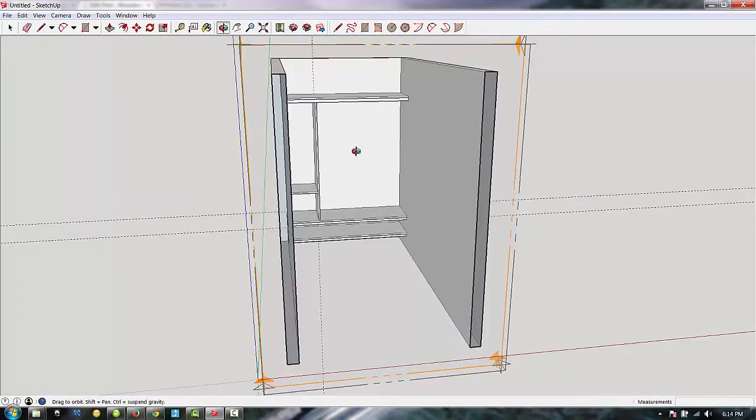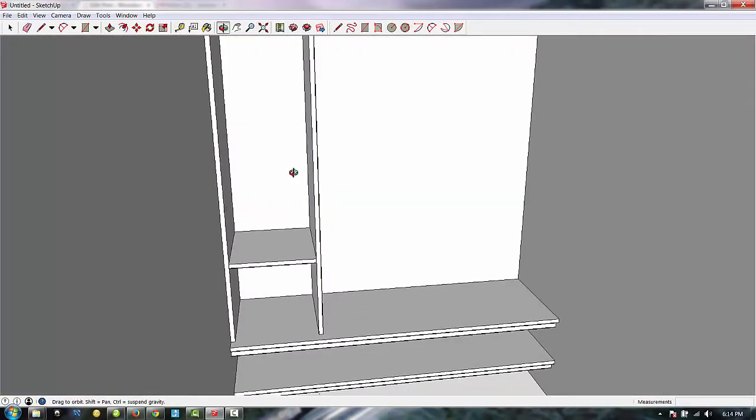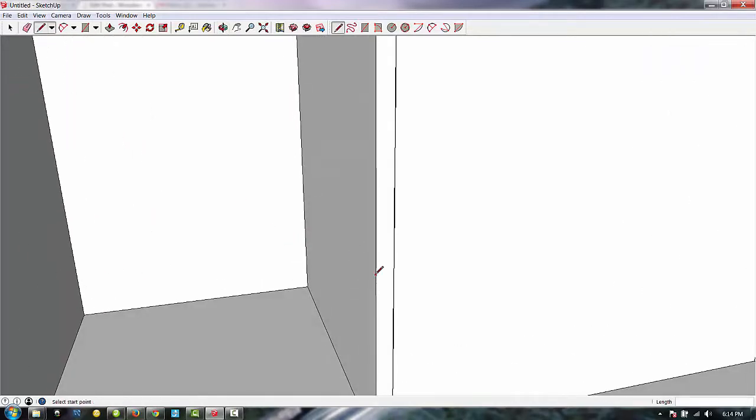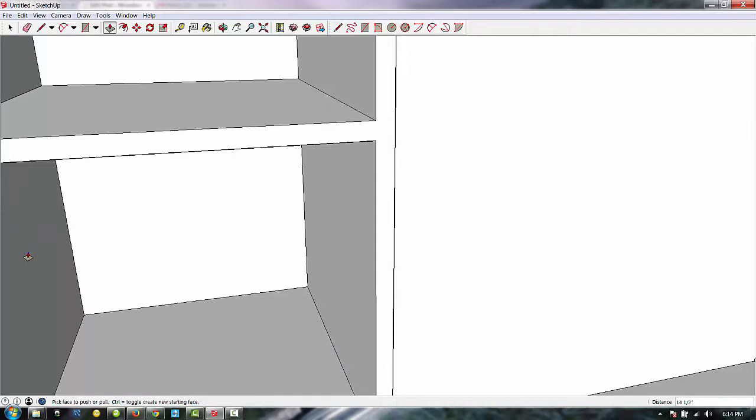Once again, in a wall, working in a somewhat tight space. I should have used the divide tool on this side to give myself a little visual space, but that's okay. So I will select that already divided section, and I picked the upper and dropped down from the upper. So again, comma 3/4, because the 17-inch length is the first of the 2 dimensions, so I do comma 3/4 to give myself that 3/4-inch shelf piece, and then I'm just touching the face that I'm going to, and that jumps to the proper point without running through the item.